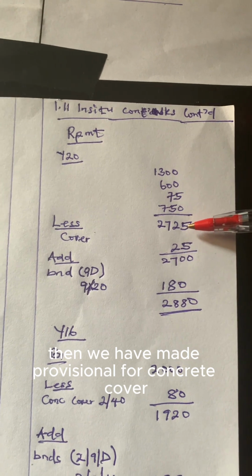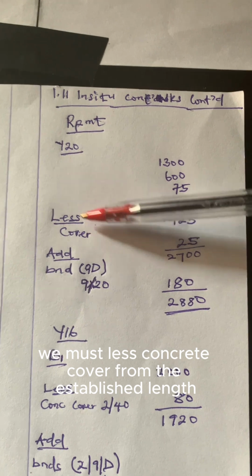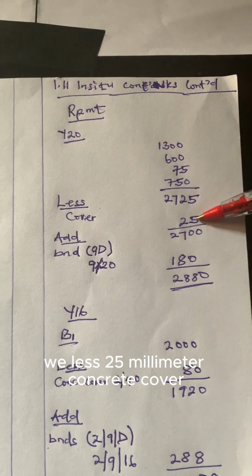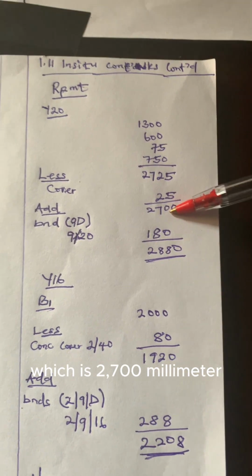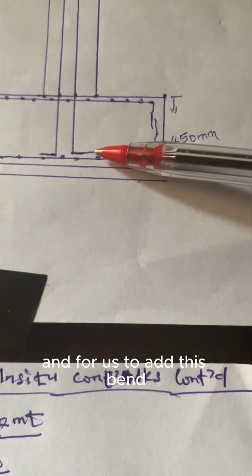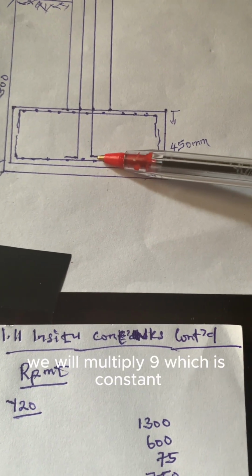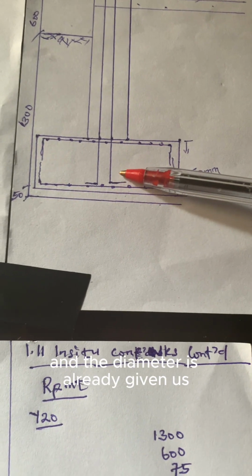2725. Then we have made provision for concrete cover, which we must less concrete cover from the established length. In that case, we less 25 millimeter concrete cover. We will arrive at this figure, which is 2700 millimeter. And for us to add this bend, since it is at one end, we multiply 9, which is constant, by the diameter of this reinforcement bar, and the diameter is already given as 20